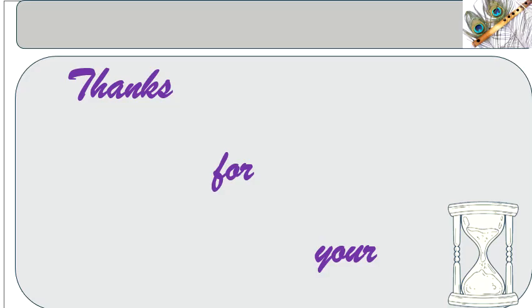Thanks for your time. Timing analysis in VLSI design is not just a verification step, it builds performance and reliability into the design. From the parasitic effects in materials and interconnects, every component plays an important role in determining the overall timing accuracy. Understanding setup and hold times, clock-to-queue delays, and the significance of timing paths helps us appreciate the precision required in modern chip design.